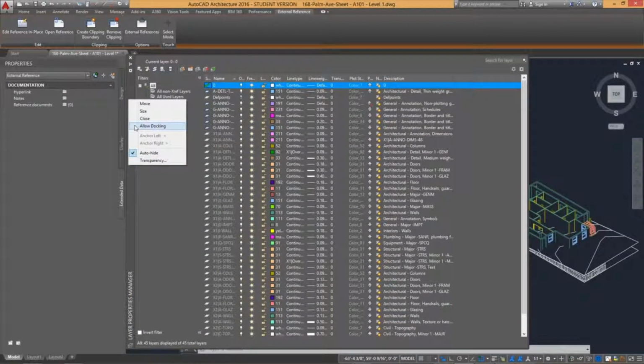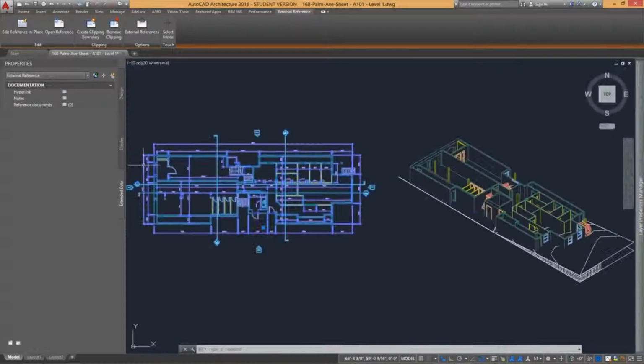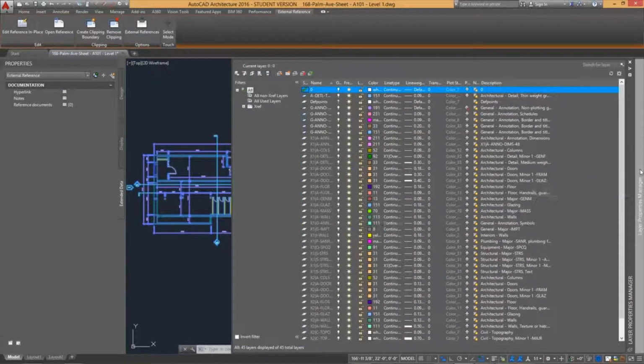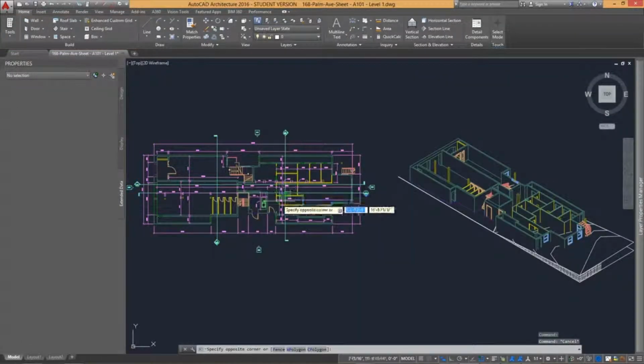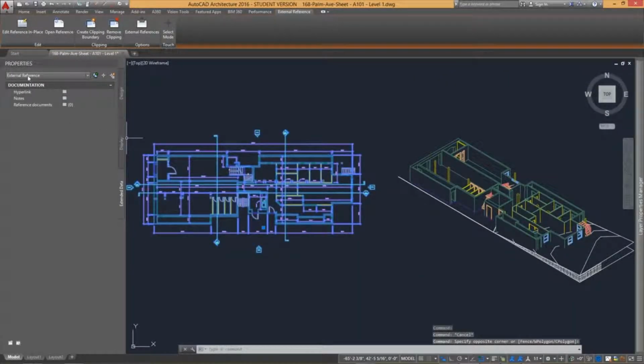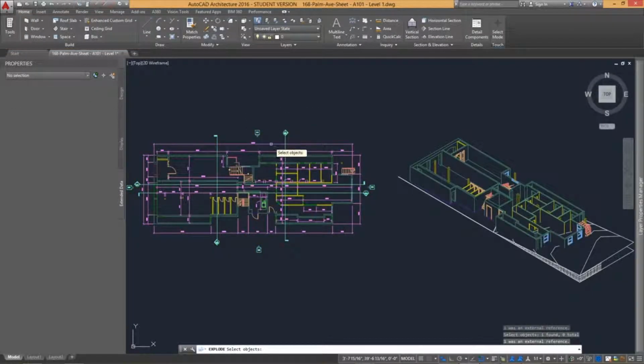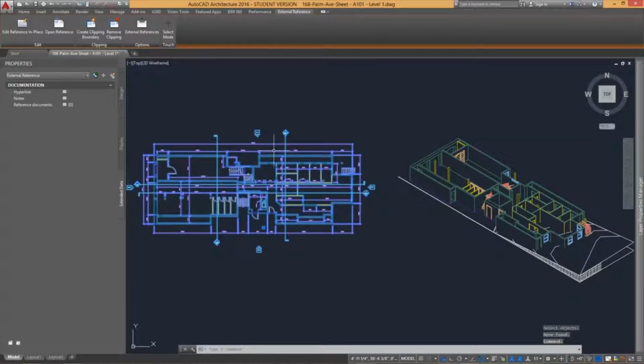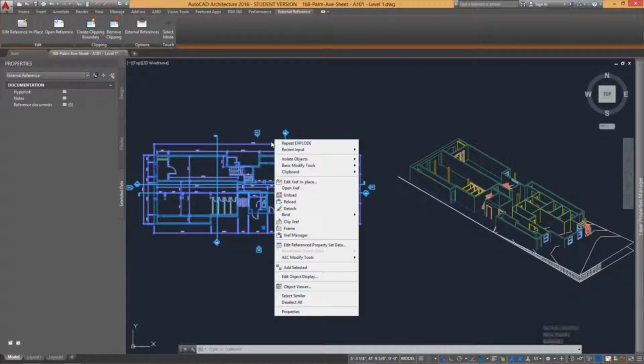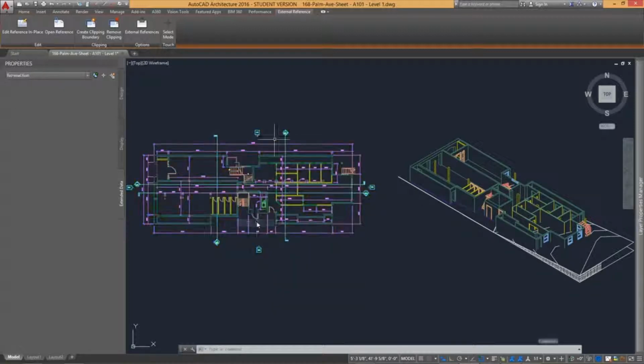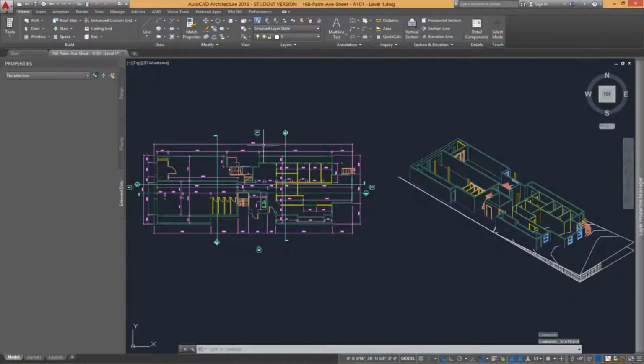We then have this automatic opening of the palette when you hover over one of the docked palettes, similar to the functionality found in TurboCAD when the palettes are not pinned. In this example, we can see from the Properties palette that when an X reference is selected, this information is shown in the palette. We then need to bind the X-refs into the drawing so that we can interrogate each item within that reference.